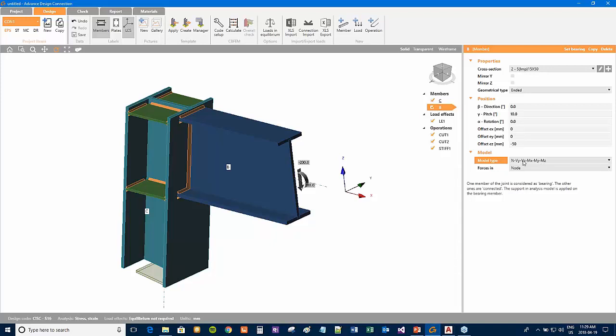So when you have this kind of constraints, you can apply the forces in all directions for this B member, but you can apply constraints at the end of this member. So you can, for example, close this direction so you will not have out of plane bending in this member. All of these limitations on members can be applied using these options here.